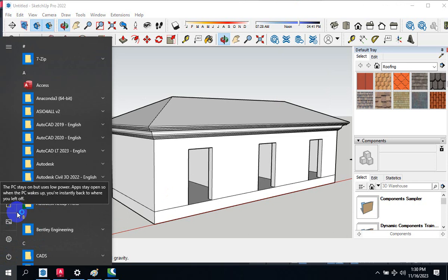So, should I take it again? No, we're here. No? Do you see it fitting the cover? So let me Control Y. Okay, fine. Now we can copy this same size of door to the other openings. To move, copy. You click on this one now, click on this, you hold on Control. Then you drop it also. That's it.